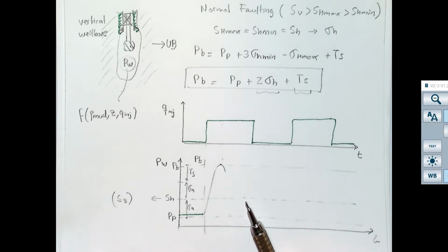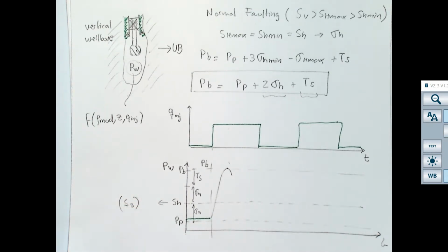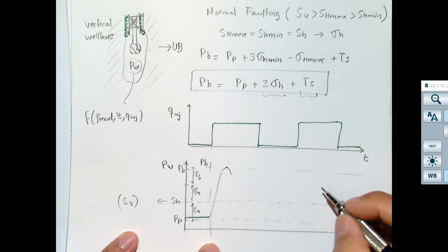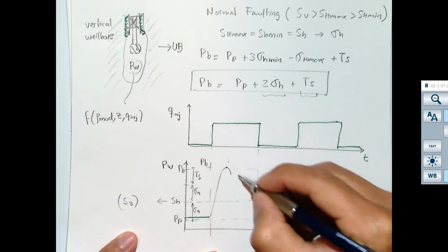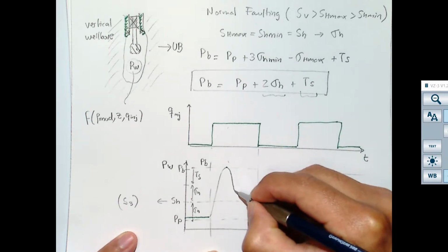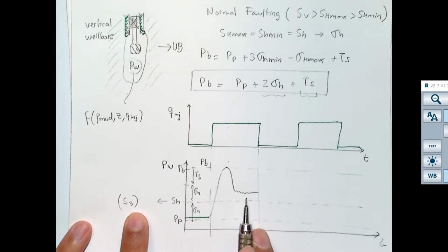So if the fracture is propagating, do you think the pressure is going to go lower than the minimum principal stress? Probably not, right? But not probably. Very, for sure, no. Because if the fracture is open, in order to be open, the pressure has to be larger than the minimum principal stress. But since the fracture is still propagating, what we're going to get to here is a value which is not quite the minimum principal stress, but it's a little bit more.